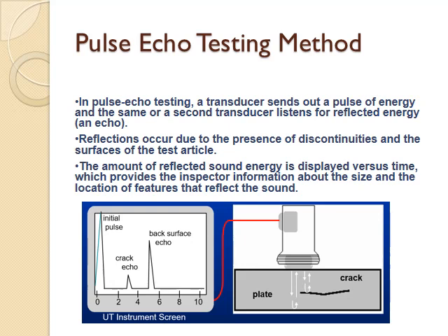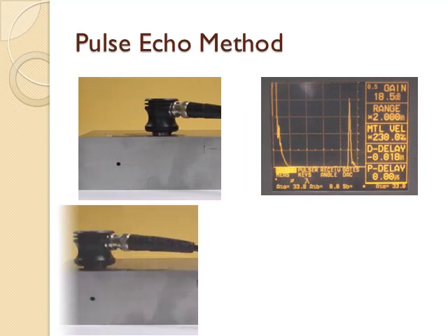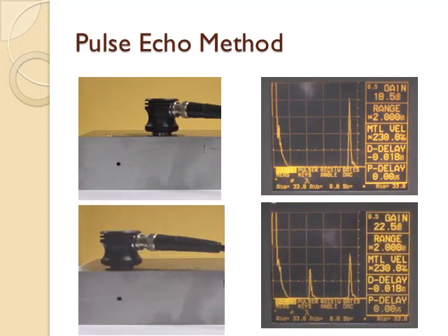Consider there is some flaw in the specimen. The pulse generator generates high frequency waves, which are applied to the piezoelectric transducer, and the same is recorded in the CRO. Name it as pulse A. It is our reference value. Then the piezoelectric signals are resonated to produce ultrasonic waves.